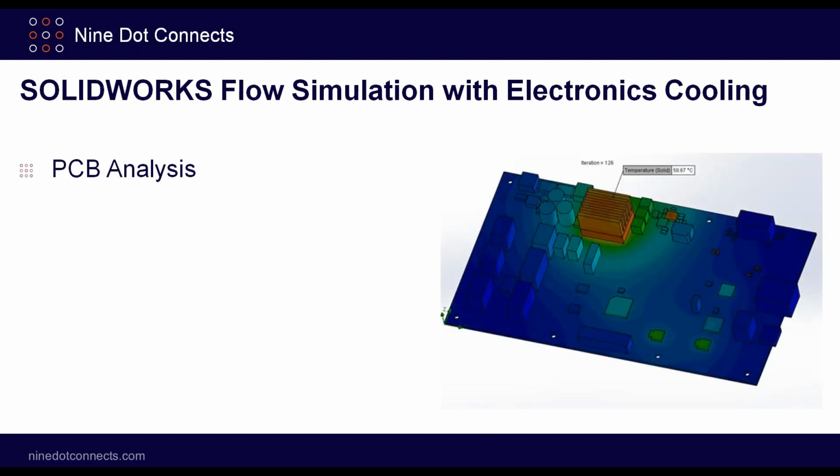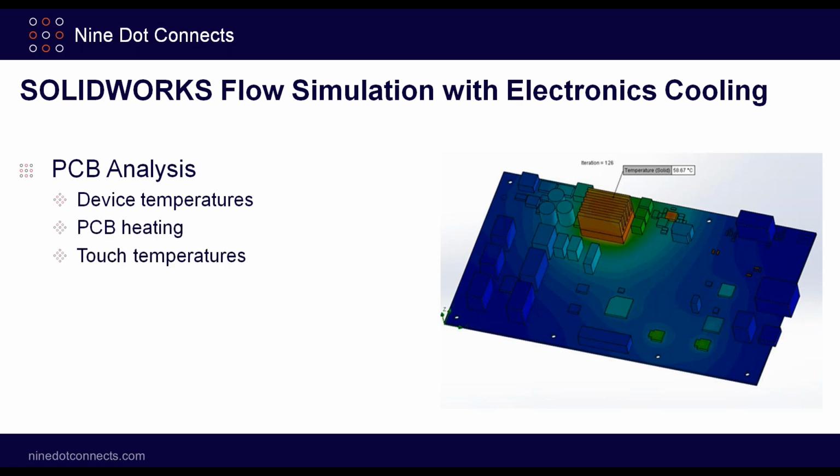And then for PCB analysis, which is what we're really focused on today, it has a long list of features. We can look at device temperature, the physical PCB heating, and touch temperatures. We can do both transient and steady state, so we can look at how long it takes to reach the temperature, or we can look at what the final temperature is of a device or a system.